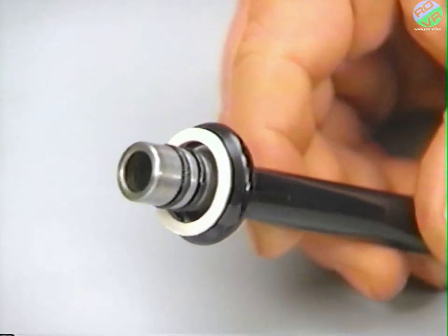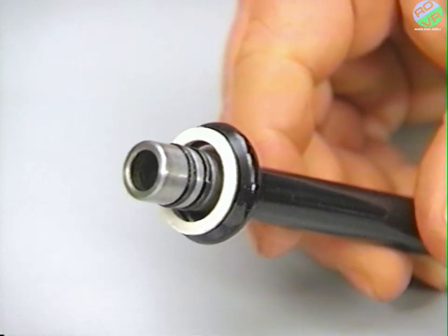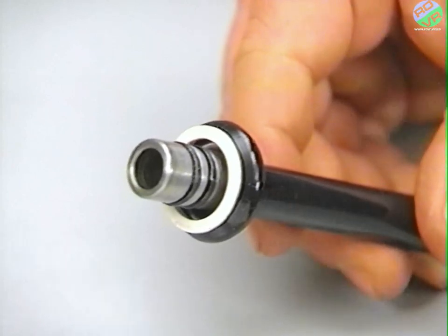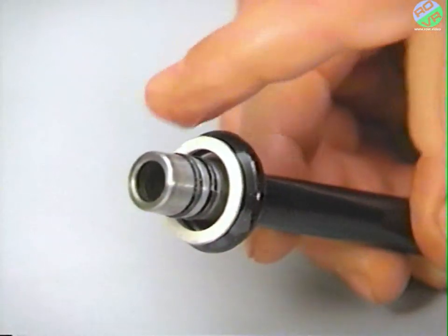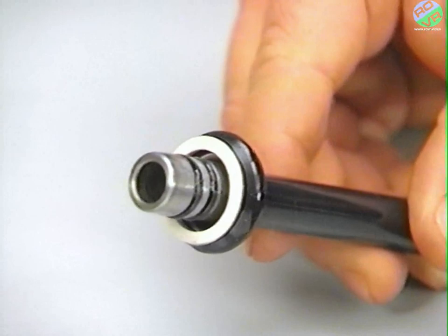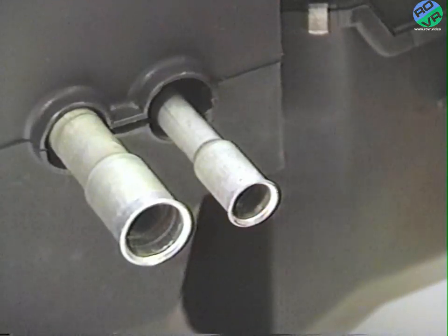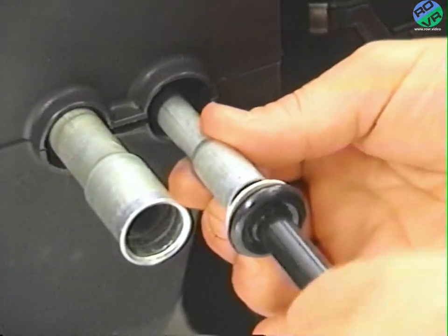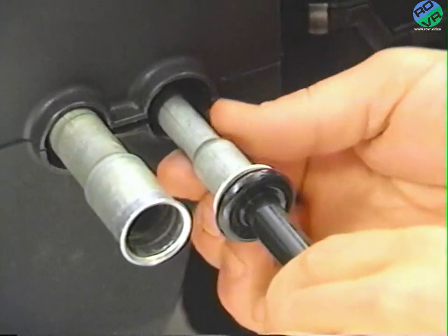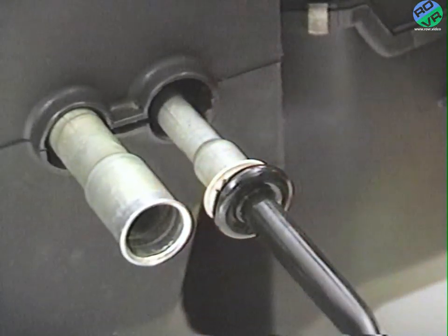Since the O-rings are made of a special material, use only O-rings specified for the spring lock couplings. Lubricate the new O-ring seals and the male and female sides of the connector with refrigerant oil. Then push the two halves of the coupling together using a slight twisting motion. When the two sides engage, you'll hear a click, and if used, the indicator ring will pop off to indicate